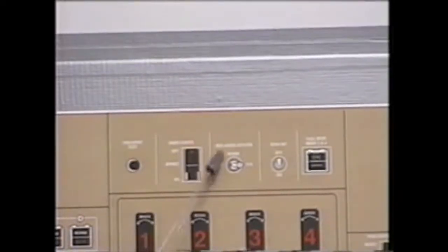Moving to the right with the emergency exit lights, 3-position switch: off, armed, and on. The emergency exit light batteries will charge with this switch in all 3 positions provided DC bus 4 is powered. If you place the emergency exit light switch to on, the emergency exit lights will come on. The batteries will be powering the lights, and if DC bus 4 is still powered, it will continue to charge the batteries. However, the discharge rate is greater and the battery charge will deplete.